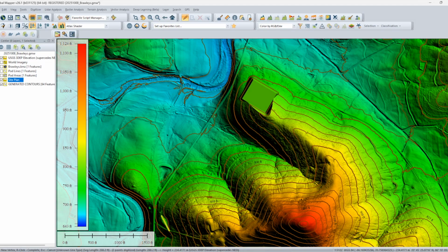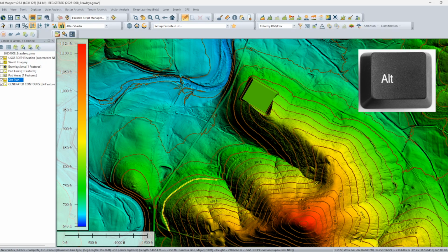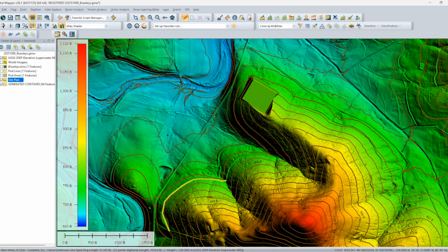Keep in mind that you will have difficulty when drawing the line when the contour layer is turned on. The line would like to snap to these lines. To avoid that, just hold the Alt button on your keyboard. It will allow you to pick any point on the map. Notice I try to stay between 2 contour lines while following the existing road because I want to keep the road on level, so there won't be drastic changes on the vertical grade.